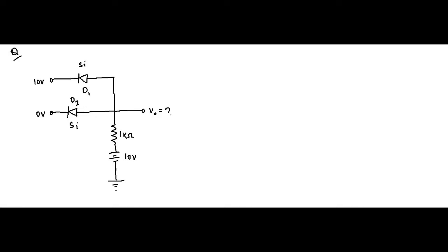I've already said that when you consider non-ideal diodes, if both ends are connected to the same potential, it will not be enough to drive the diode into forward bias, because the built-in potential will not allow it. So in this case it will be off,